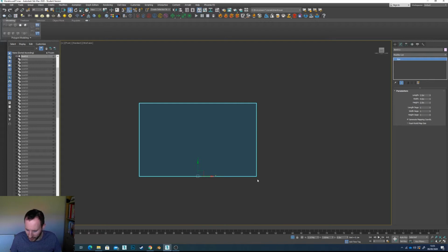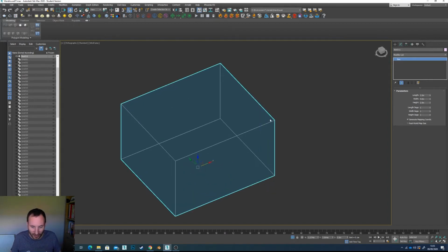What we're going to do now is start cutting out all the parts we need. But a bit like when we made the warehouse, we're going to basically detach the walls of the office, because otherwise you can get issues when you're trying to do your cuts across the whole box. Also, when you add a thickness to your walls, if you try to shell it, you'll have issues with these corners, especially once you've cut into them as well. It can cause all sorts of problems that you don't want to get into.